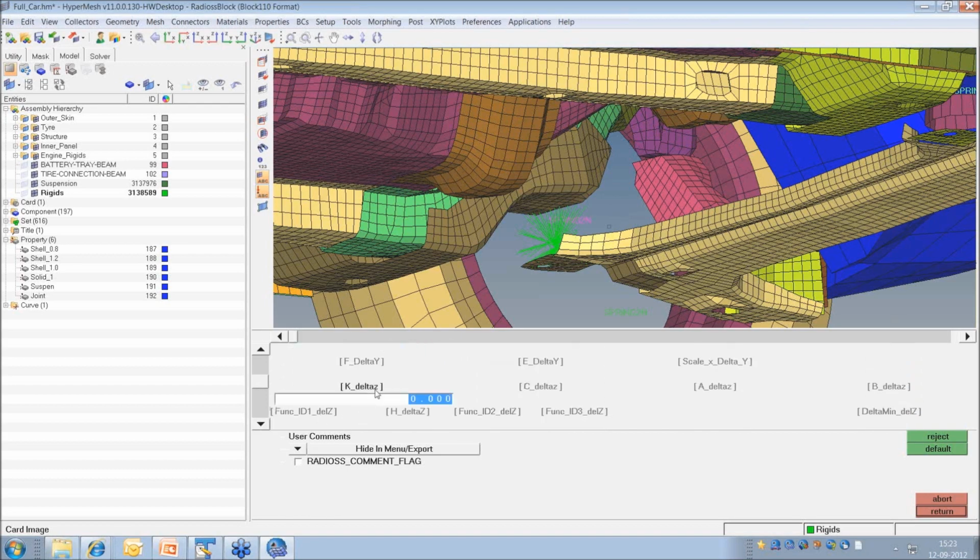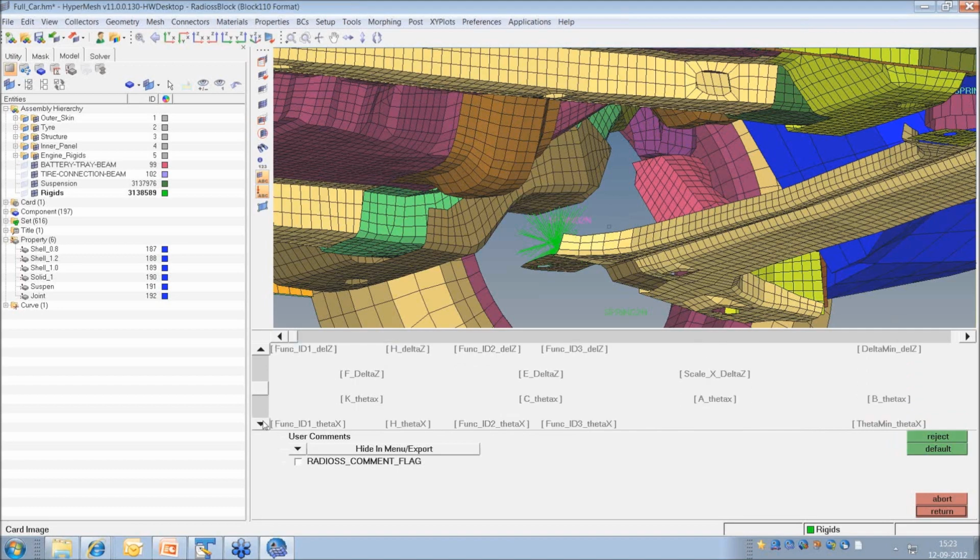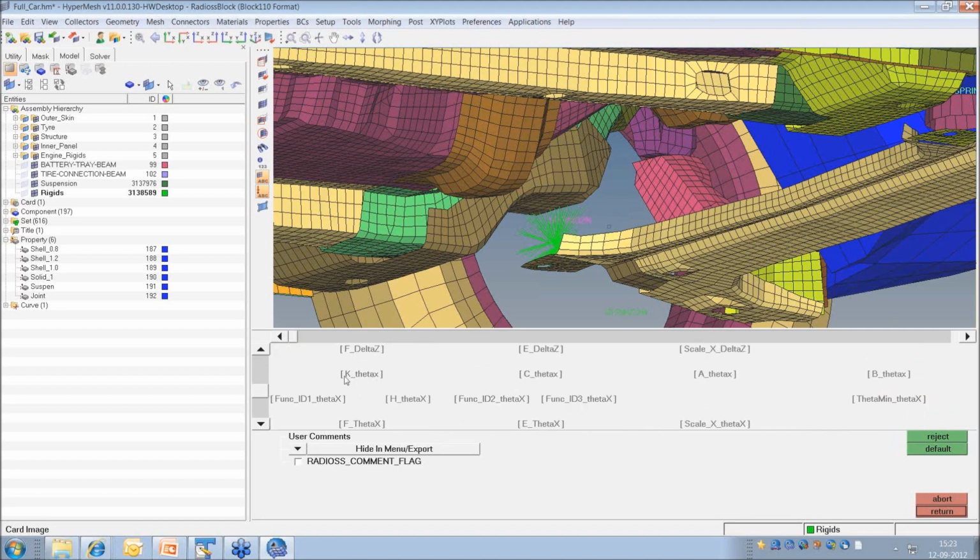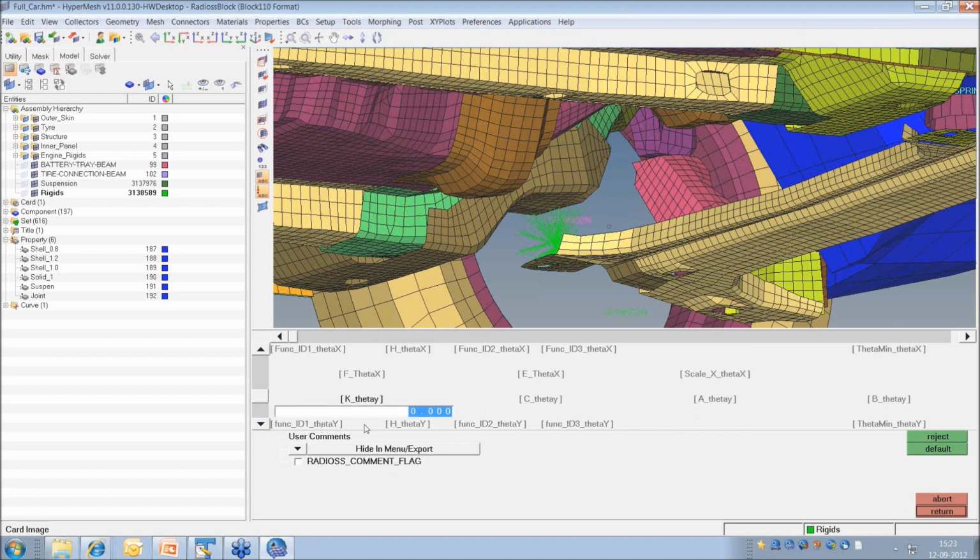This is along z, again high stiffness. Okay. So as I mentioned, in z rotation, so this is along x rotation, which is again high stiffness, and y rotation again high. So this is the z rotation, which I will keep as 0. So for this spring to rotate in z direction, there is no stiffness, so that it can easily rotate and work something like a joint. So this is how I am creating a joint.